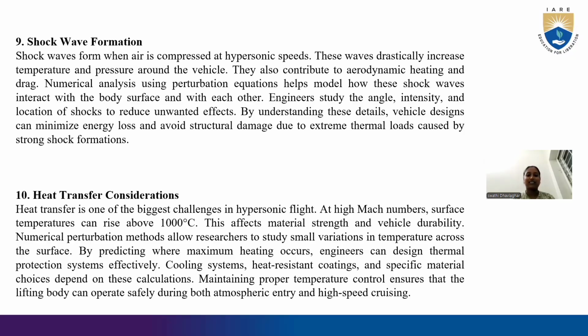By understanding these details, vehicle designers can minimize energy loss and avoid structural damage due to extreme thermal loads caused by strong shock formation. Heat transfer consideration. Heat transfer is one of the biggest challenges in hypersonic flights at high Mach number. Surface temperature can rise above 1000 degrees Celsius. This affects material strength and vehicle durability.